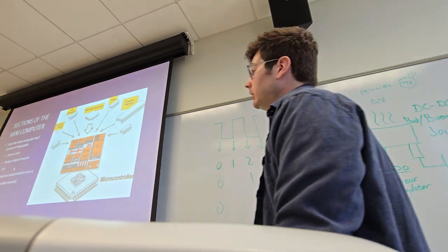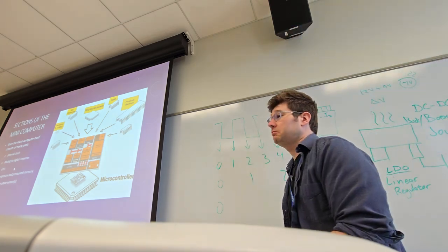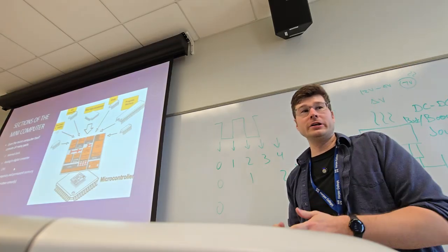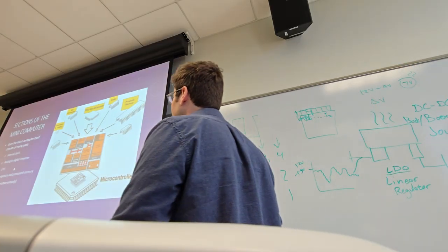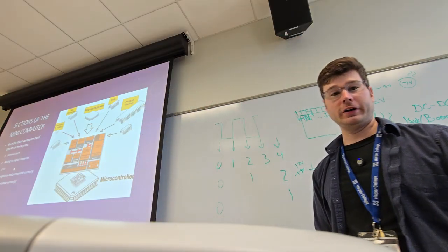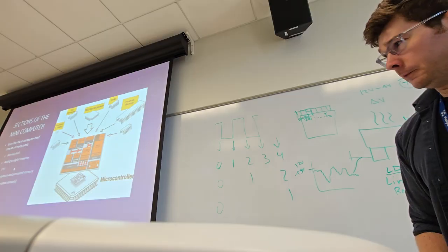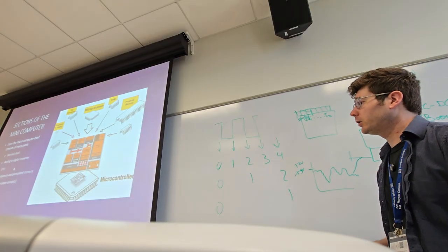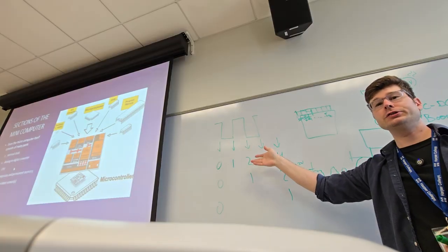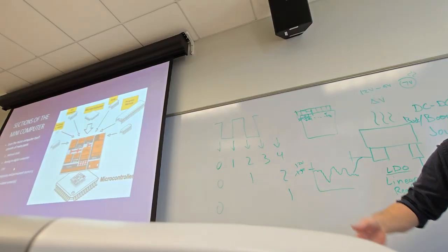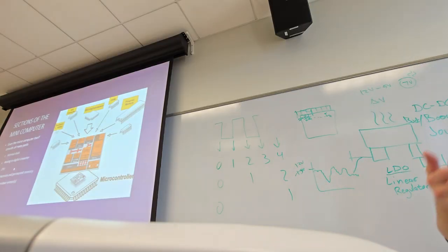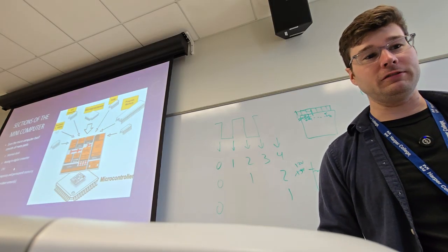There may also be things like temperature sensors in there. If it is a particularly high-performance processor that can overheat or needs to underclock itself, you'll have a temperature sensor in there, as well as many other kinds of peripherals that I didn't mention. There are simpler, really low cost processors that X out half of these things. They just don't need it for the application, so it's cheaper to make it without. And there's things with 5 times as many, right? More I/O pins, more peripherals, more timers, whatever needs to sell.